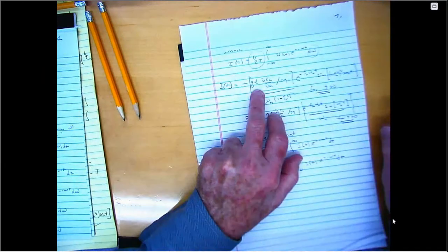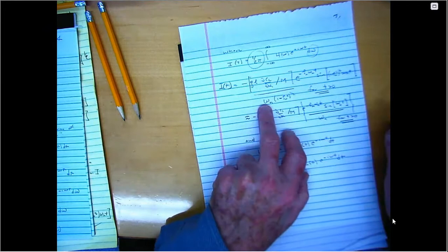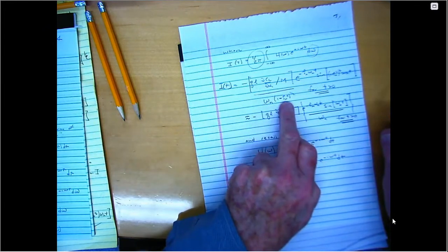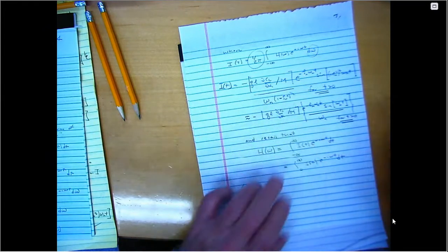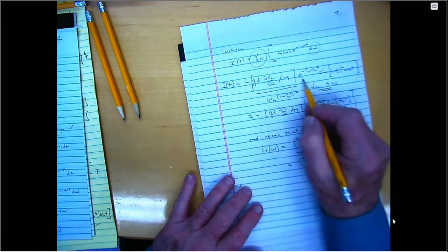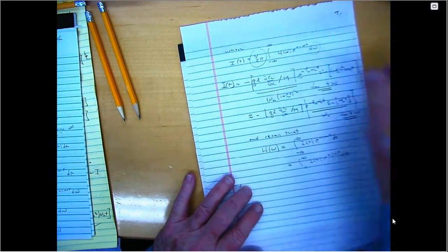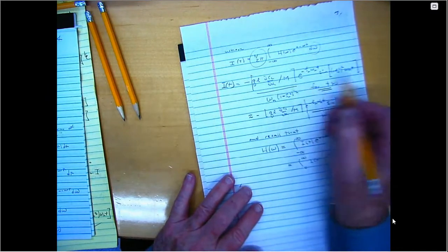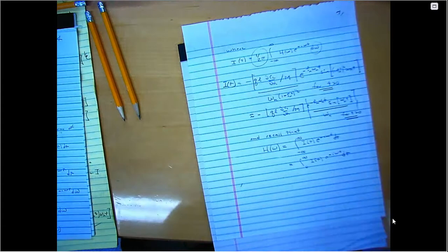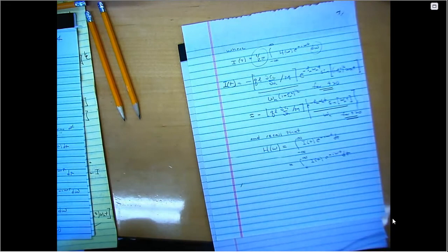involves the dynamic pressure, the span of the wing, the lift curve slope, the mass of the wing, the natural frequency of the wing, the damping ratio of the wing, a damping ratio associated with air density, and then most importantly, e to some negative factor times a sine. So what is this physically? It's a damped oscillation. Right? This system is stable. It has positive aerodynamic damping. It doesn't flutter. This model doesn't flutter.